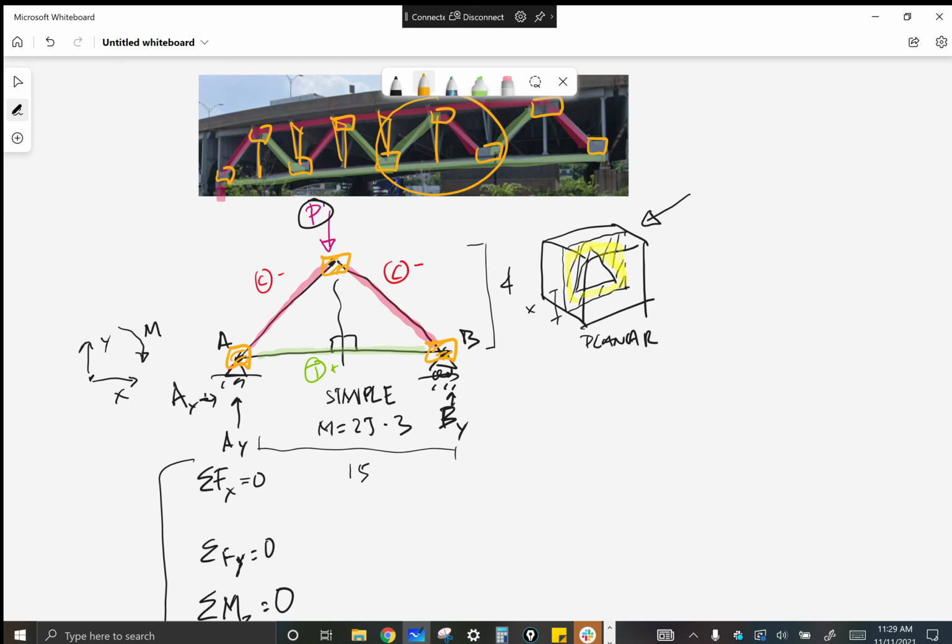So another question might be something like, what is the strength of joints in simple planar truss theory? Or how big are they, something like that, just so you get the idea that they are there only because they have to be, because you have two members coming together, but they're not theorized in any way. So they're infinitely strong. And infinitely small. Exactly. They exist because we have a real world and we know they're going to have to exist.